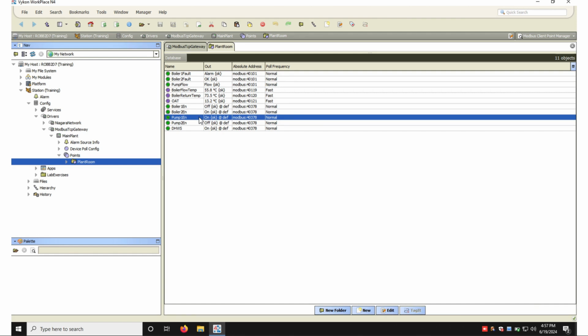The I/O module will more than likely have a default state, a fail-safe position, which will be off for the outputs. And then the I/O module is going to sit there waiting for Niagara to tell it what to do. But by default, the writable data is on change of value only. And that means it will be waiting until 5 o'clock for the next command of off to do something.